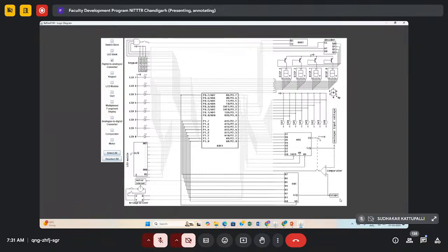So this can be used for displaying various sorts of waveforms as well. Suppose you are giving 1, 0, 1, 0, I'm talking in terms of FF and 00. So you can get a square wave, right? Suppose you are incrementing the number, subsequently you can get a triangular wave. So different types of waveforms can be generated on the oscilloscope. Any wave, you basically need to work on the digital data.